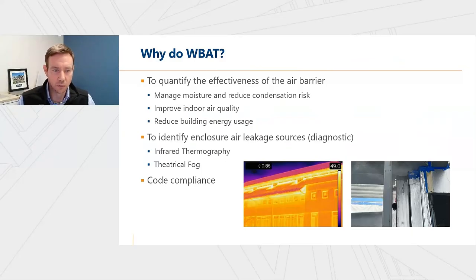So why do whole building air leakage testing? The first reason to do it is to evaluate the performance of the air barrier by getting a quantitative value of the air leakage rate through it. Less air leakage means a better performing air barrier, including for the benefits discussed earlier, such as managing moisture, reducing condensation risk, improving indoor air quality, and reducing building energy usage.